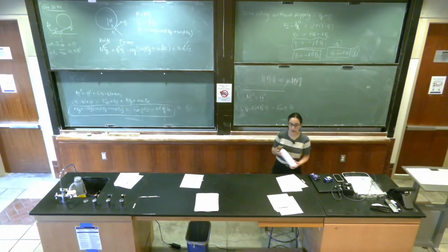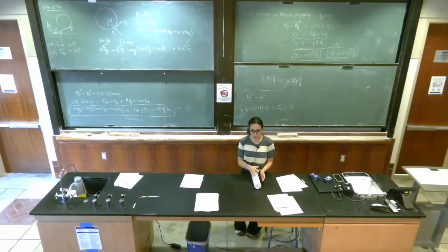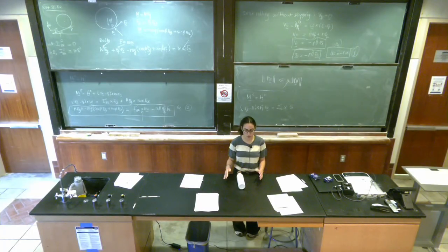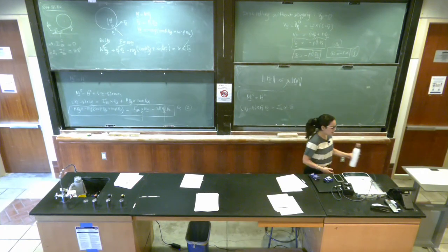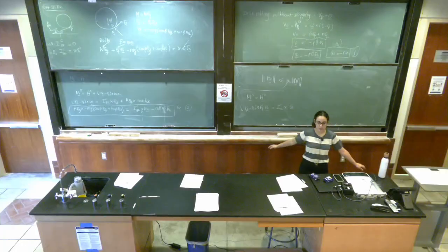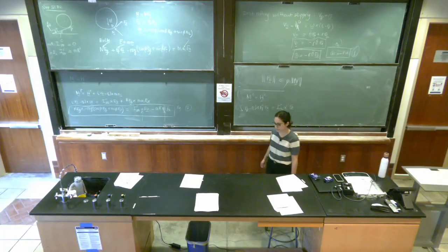So here, when the angular velocity is constant, the friction force is going to be 0. The friction force is equal to H dot, which is I alpha, but alpha is 0, so the friction force needs to be 0, being the only force giving a moment about this point. Okay. Any other questions?